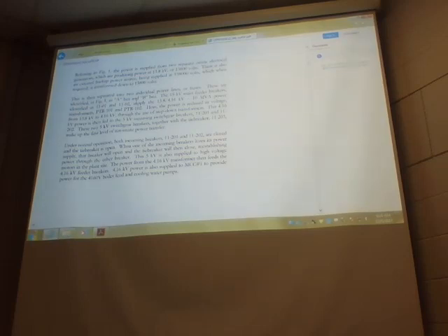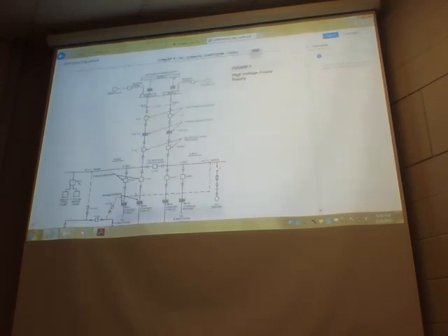This 4.16 kV power is then fed to the 5 kV incoming switchgear breakers 11201, 11202. These two 5 kV switchgear breakers together with the tiebreaker 11203 make up the first level of automatic power transfer. So now we're looking down the two 5 kV switchgear breakers, and the tiebreaker switchgear is here.